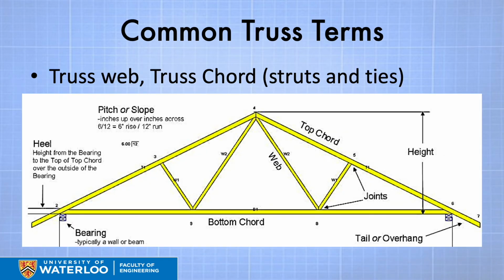Another kind of element that we use is built up of actually multiple struts and ties and bending elements. So we're going to be talking about trusses a fair bit, and the truss has its own language. Those diagonal elements connect a top chord to a bottom chord. We don't talk about a top flange and a bottom flange when it comes to trusses.